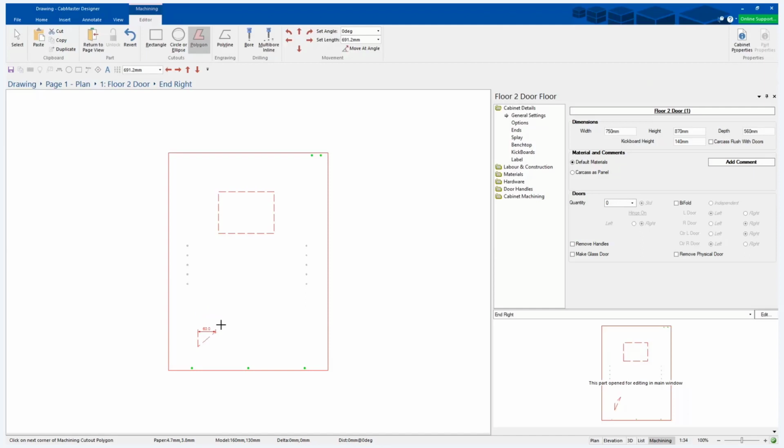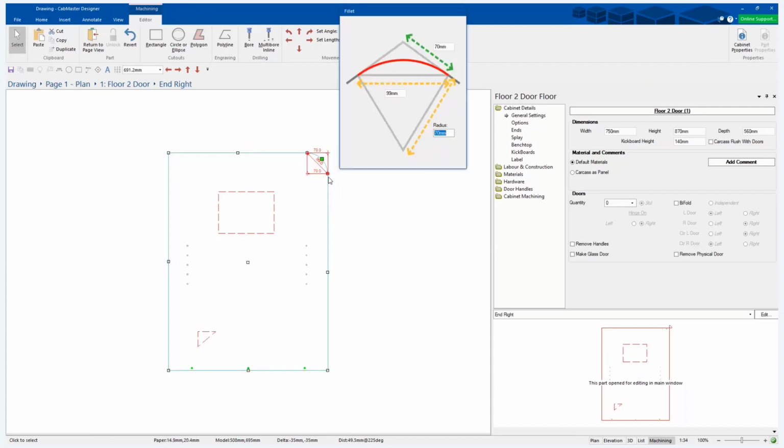So you can quite happily do these quick lengths, as we call them. You press the down button here, and these are the quick lengths. You can set these to whatever you like. This could be 100, this could be 250, things like that. You can set your quick length in here. So then when I start drawing something, same as if I go to fillet corner, I should be able to hit 2. No, I can't, because it starts typing in there. Okay.